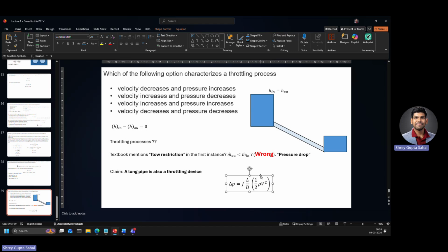The flow rate at any position is the same at any time, so there is no local acceleration happening, and there are no inertial forces. Let's just go by my statement that there are no inertia forces in a pipe, and there are only two forces: pressure force and the viscous force.